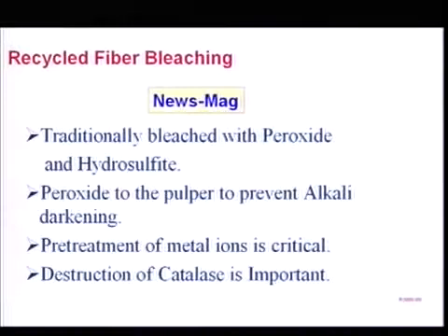In the case of news magazine, you have more mechanical fiber coming in, less dyes. Some yellow color fiber, telephone directory is there. These are traditionally bleached with peroxide in the pulper and hydrosulfide at the end. Peroxide in the pulper prevents alkali darkening.